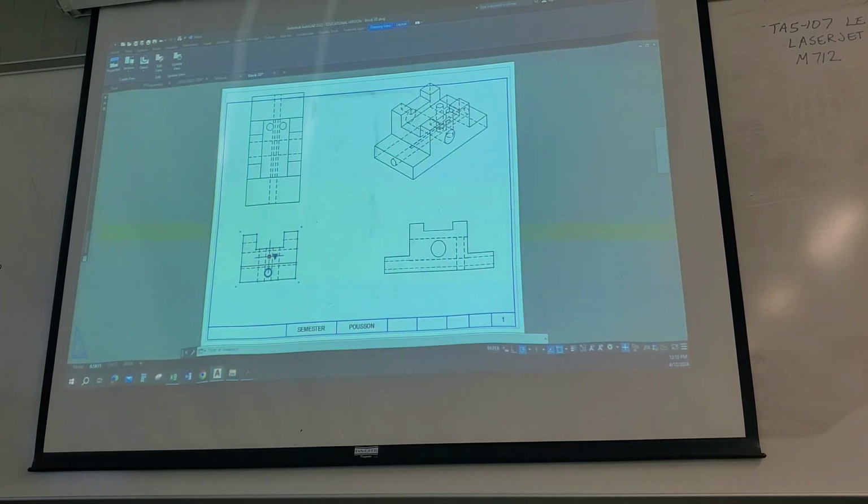I've got that blue box grip right here, standard square blue grip. I can click on that grip, which allows me to pick it up like a handle. Watch what happens if I move this view to the right. You will notice my top view is moving also, because AutoCAD knows that orthographically those have to be lined up